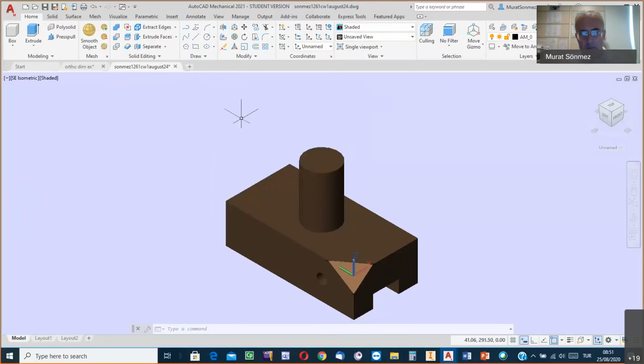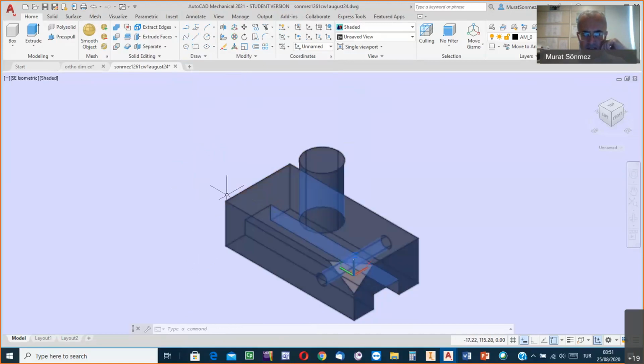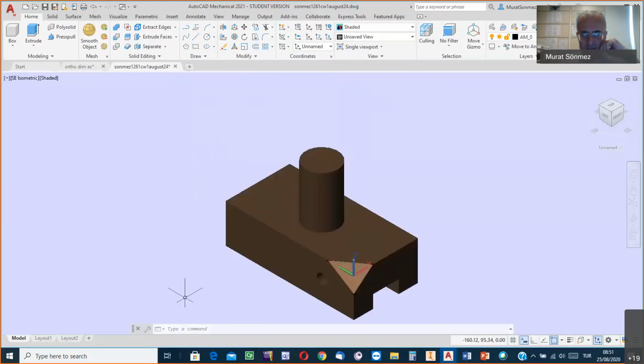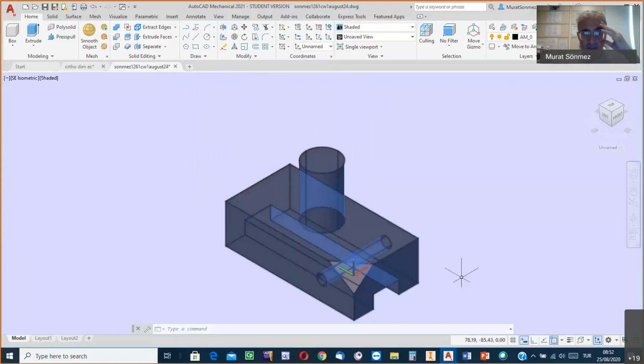But if the profile to have is a rectangle, then use the rectangle creation tool, this tool, to have the bounded area automatically recognized as a region. After creating a rectangle, apply the extrusion process to have the base of this prism. Then I said that to be able to add new features, there is a difficulty in AutoCAD: the coordinate system.